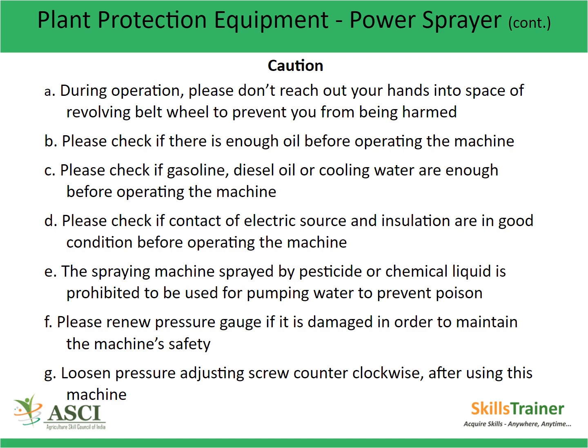The spraying machine used for pesticide or chemical liquid is prohibited to be used for pumping water to prevent poison. Please renew the pressure gauge if it is damaged in order to maintain the machine's safety. Loosen the pressure adjusting screw counterclockwise after using this machine.